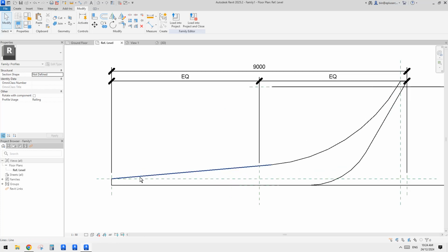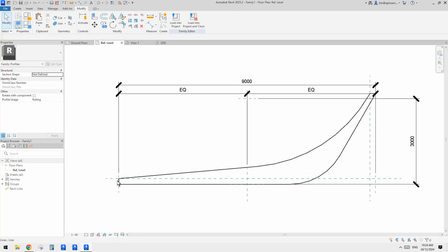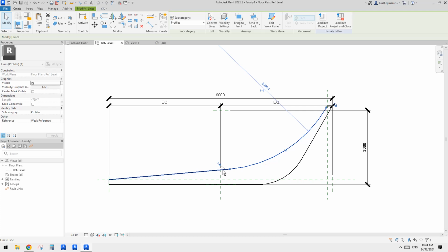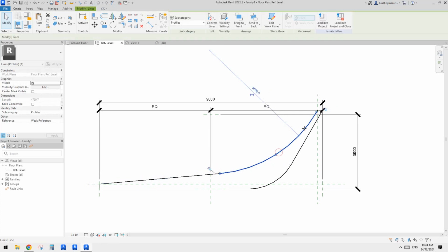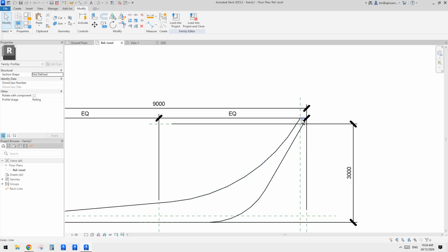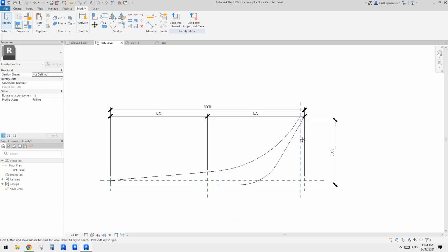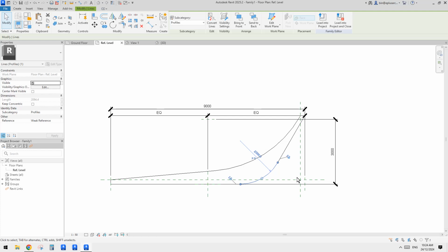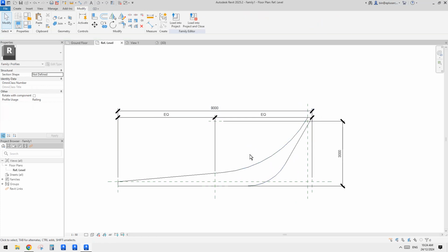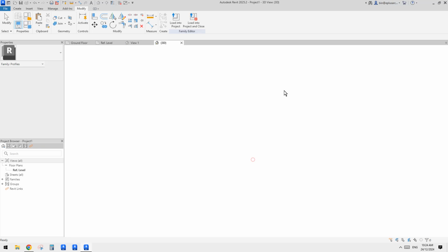You want to control the angles. You might need to add a reference line, add a rotation, add a radius parameter, and then you also need to make sure all these tangents work, and then you add another angular parameter here. So another radius here. So it'll be a lot of work, but probably it's easier to just change the shape to whatever you like, and then load it back and overwrite.